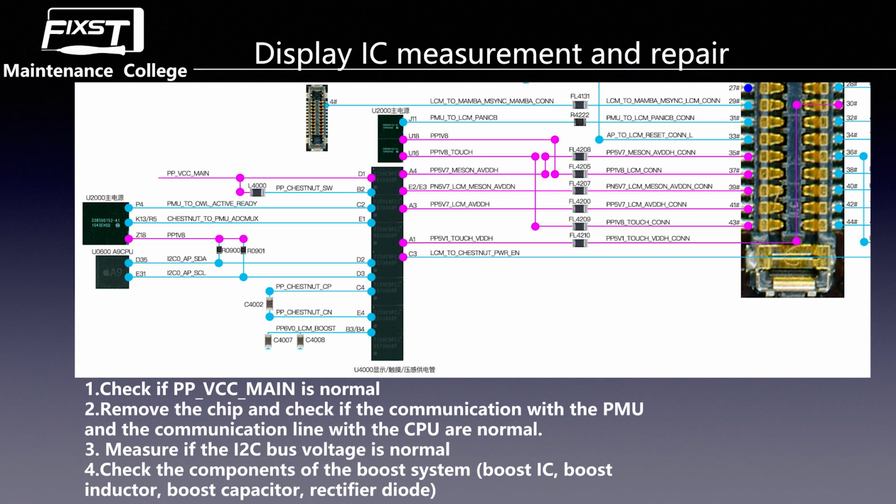So after you change the IC, if it still does not work, you need to test the booster inductor and booster capacitors. These four components, you need to change these four components and test one more time. Okay, this is how to repair the display power IC.